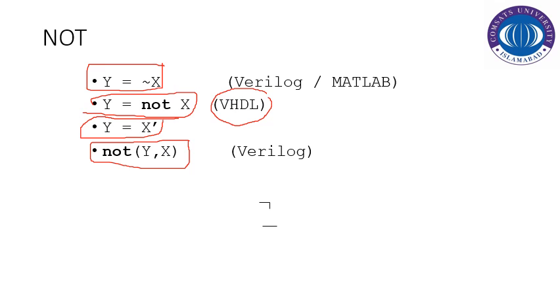Since you haven't studied Verilog, I'm not using those terms, for example the primitives, the gate level primitives, and the modeling techniques which can be used to describe any digital component. So to conclude, the NOT gate basically inverts the status of your inputs. If you apply 0, you get 1, and if you apply 1, you get 0 at the output.